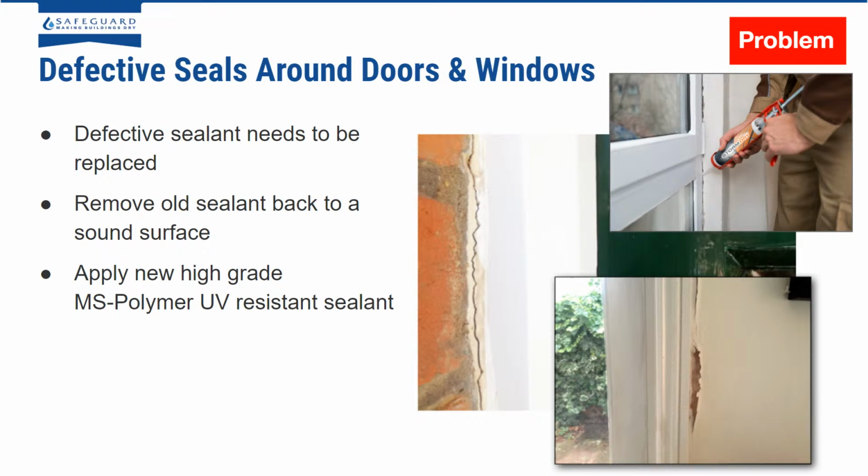Question we often get asked, Marco, on this subject, I hope not to put you on the spot too much, is which order would you apply a sealant? Would you apply the sealant first and then apply Storm Dry, for example, or would you apply Storm Dry and then the sealant? In most situations, we would recommend applying the sealant first. In terms of any structural work, it's good to fix any defects such as windowsills and repointing work first, and then apply Storm Dry. As Storm Dry makes the wall slightly water repellent, it may affect the adhesion of some of these products.